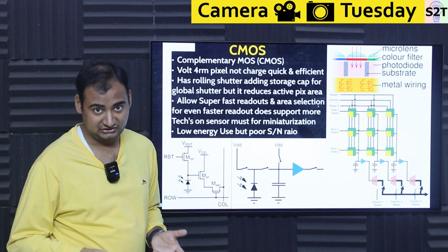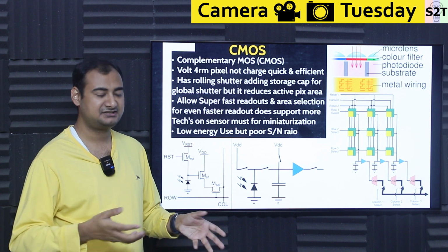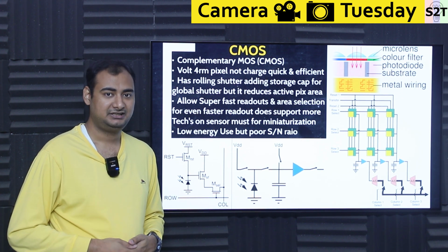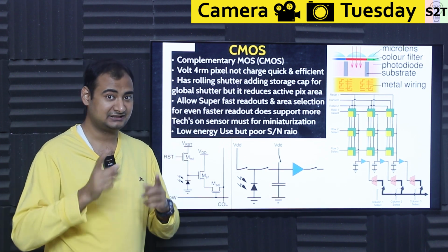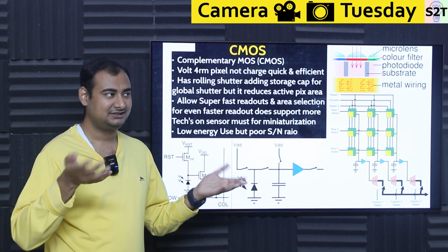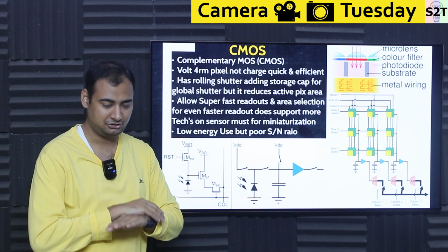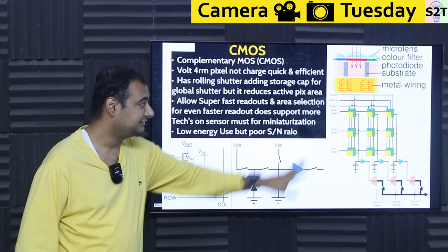However, in some use cases, especially in machine vision, you may say, hey, that's not acceptable. Imagine feeding that rolling shutter data to your car-driving AI. The AI would be confused. It's like, why the hell are things going wobbly? And be mindful that the wobble is directly proportional to your speed. So as the car speed increases, your car's shape will literally change. So fundamentally, that's not a go. Same goes with machine vision used in factories. It's like, no. For that reason, we have this puppy.